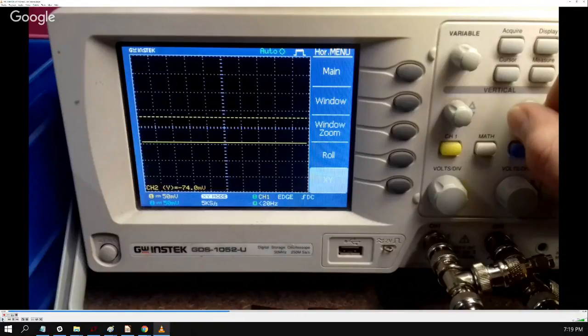So in this oscilloscope, I switch between a rolling visualization and an XY plot. You can see the actual signals in time, but you can also see them as a phasor. I will show what happens as you change the modulation type, and you'll see the phase locking occurring because the beat frequency will disappear.